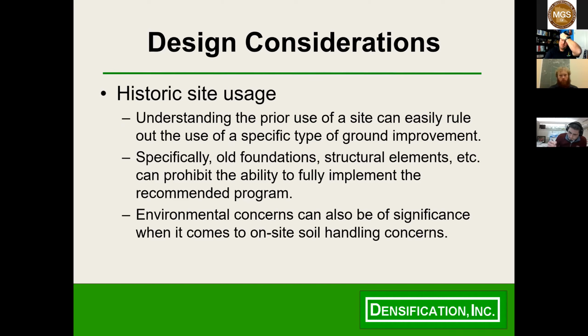So, from a historic site usage, understanding if there are old foundations, old structural elements, environmental concerns, right? If there's a lot of foundations in play and concrete in the ground, dropping a weight on that is more of a demolition activity than a ground improvement activity. And that could be a real problem from a carrying-the-program-out approach. And then again, the environmental concerns, knowing how to handle the soils, do they need to stay on site? All things that play into designing your program.